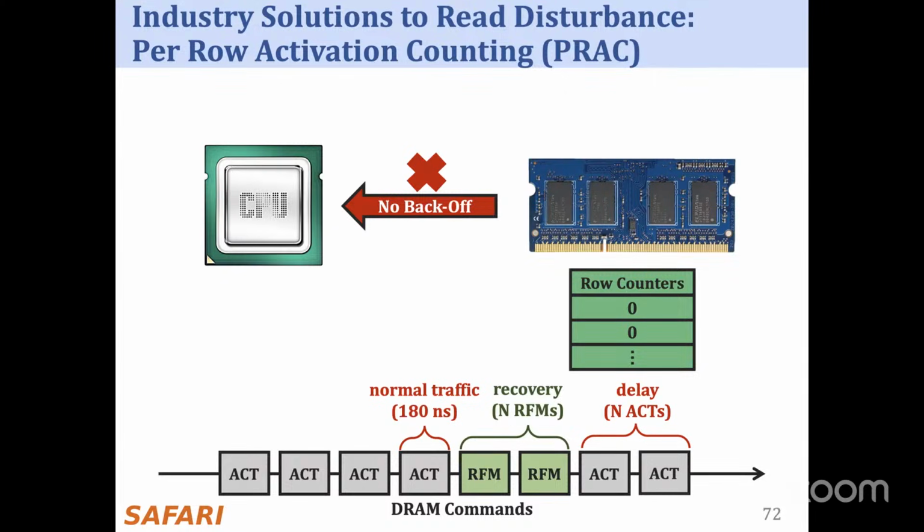Alert. That alert means that basically something is seriously wrong. This is because we don't have a very good interface between the memory controller and the DRAM chip. The memory controller needs to decide everything. And then when the memory controller somehow figures out that the chip is dying, because internally some things need to be refreshed, the memory controller says, okay, now you can do refreshes. It's a very bad way of designing the interface if you think about it.